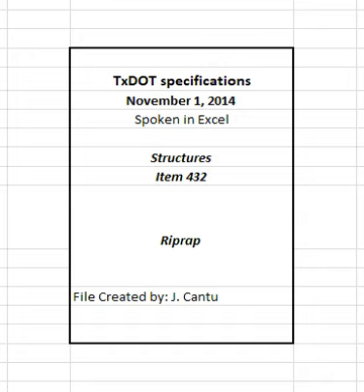Sieve size 3 inches with 100% by weight passing. Sieve size 1.5 inches with 50 to 80% by weight passing. Sieve size 3/4 inches with 20 to 60% by weight passing. Sieve size number 4 with 0 to 15% by weight passing. Sieve size number 10 with 0 to 5% by weight passing.